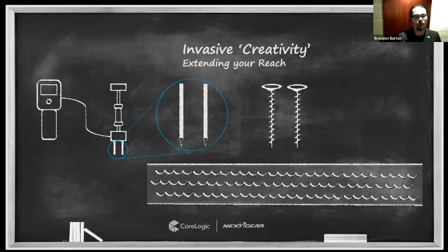If we're talking about posts and beams and other materials that are typically much thicker than the range of your standard instrumentation, then the invasive meter can be used with appropriate fasteners and drill bits or other metal electrodes in order to access deeper into those building materials. And then those electrodes can be left in place throughout the duration of the drying process, and we can re-inspect at that same exact location over and over again.